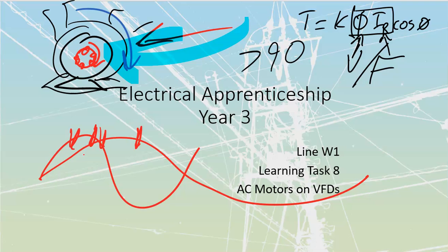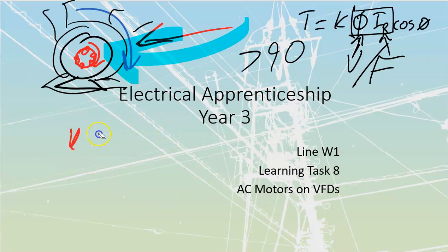Anytime that we are working with these motors, we talked about inverter duty before. Inverter duty is also oftentimes going to require us to have larger circular mill area, just because we have these more rapidly rising, especially PWM type of waveforms. We're going to have more rapidly rising front edges, which means that we're going to have more skin effect, where we're driving the electrons out towards the outside edge and getting less that's going to be carried across the center of these ones.